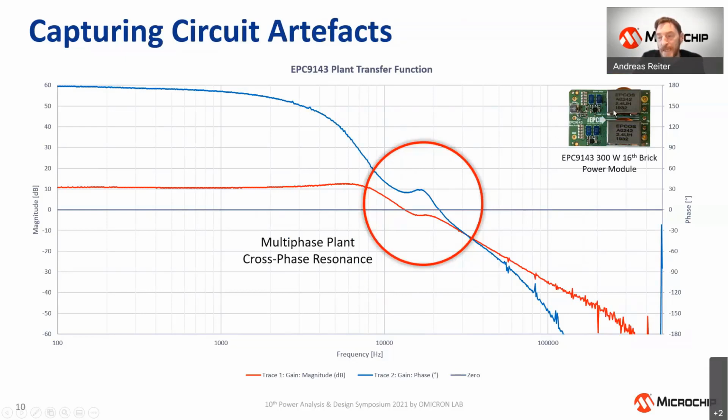And so the two phases are operated 180 degrees out of phase. And so you have the two resonant points of each of the converter phases. But the two resonant frequencies also, due to extremely low damping and very high efficiency, start to add up. So at twice the resonant frequency, we suddenly saw this funny bump and jerk showing up.